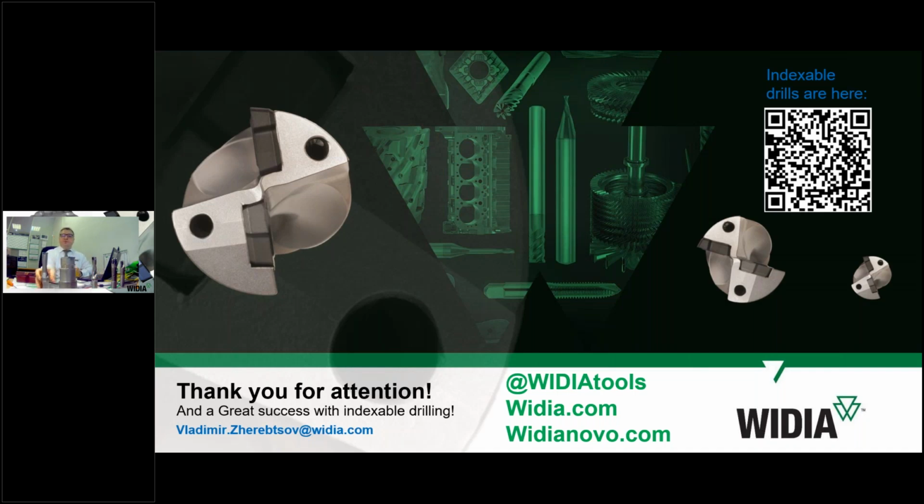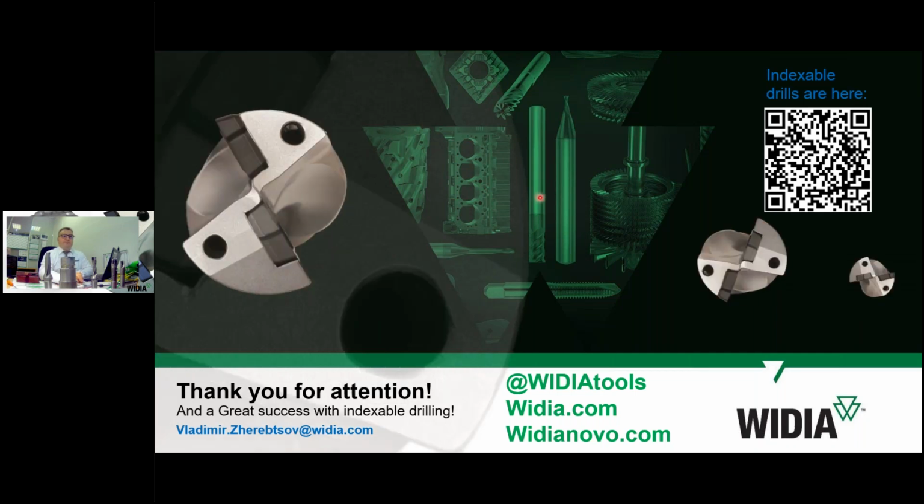If you are, for example, machining 4 diameters, there can be overheating of the top, and it's critical for the steel part of all tool body drills, if I can say so. So you can check, but the better recommendation is to avoid dry cutting, or if you do it, only on 1 diameter or on horizontal machines, and better to work with short chip materials.